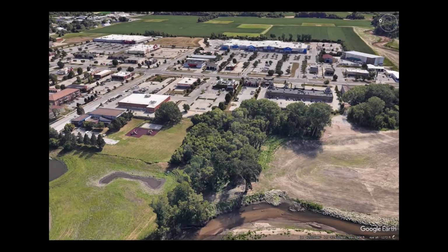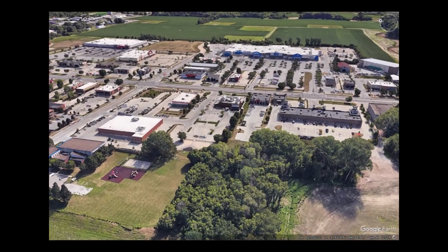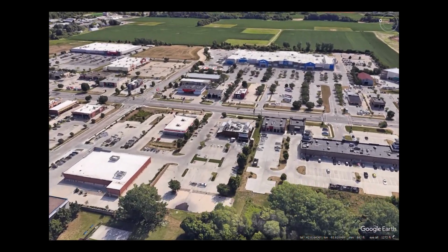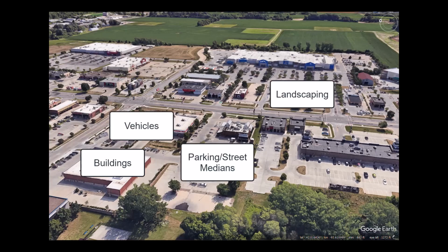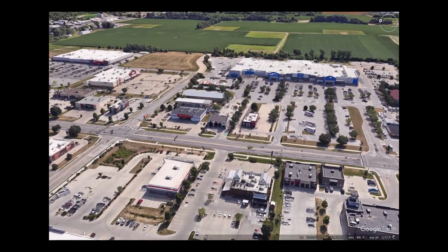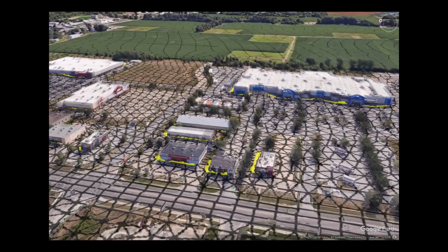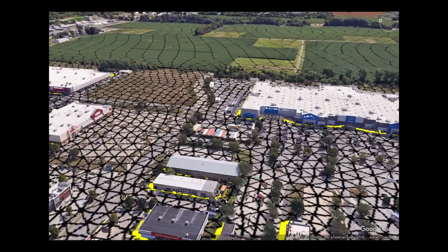Urban areas present a unique challenge to assigning roughness values to hydraulic models due to the many different types of land use, including buildings, that impact hydraulic results. Like other model parameters, it is important to understand what the application of the model will be so the appropriate approach can be used to represent buildings.